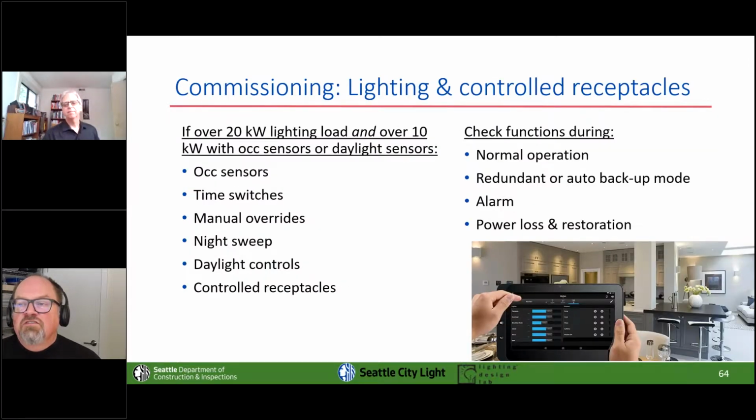Duane, yes. Do solar roof areas allow for solar heating systems as well? By solar heating, you mean solar water heating? I'm assuming, yeah, it's preheat for domestic water. Yeah, and a decade ago, I was very much in favor of that. PV was expensive, and you could get a lot of energy per square foot of roof space from solar water heating things. Now, with the cost of PV plummeting, and especially given that they have a very long life,